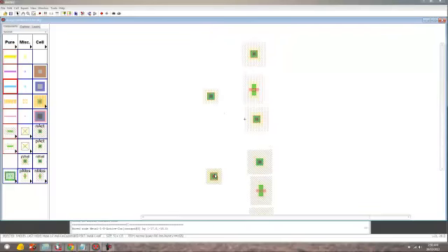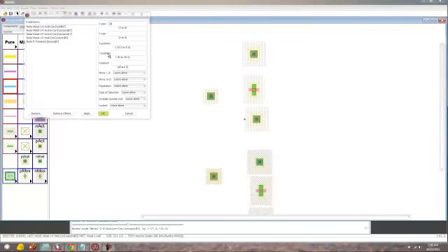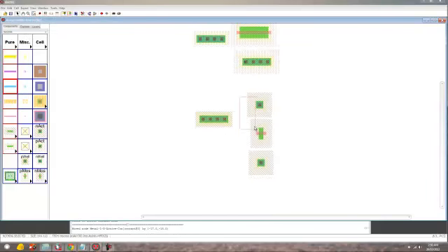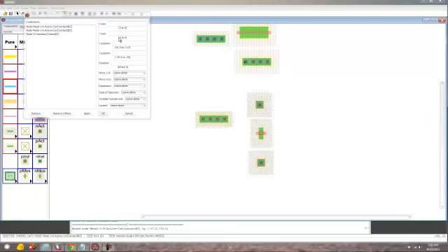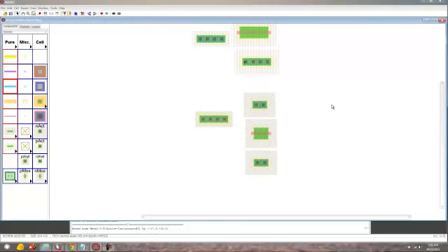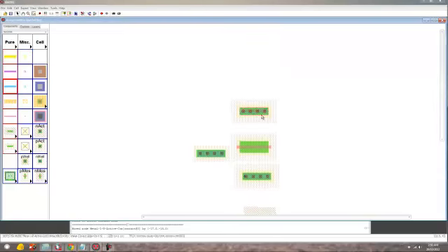So select the P well, N well, PMOS, and press Ctrl I and change the width to 20. Do the same to the NMOS but change to 10. Align the P active to the PMOS. Make sure the spacing is at least minimum 3 so that it abides by the MOS rule.